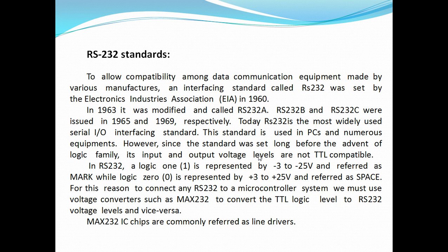These TTL levels are used for microcontrollers for data transfer, but the RS-232 standards were designed before the invention of the microcontroller. The RS-232 standard uses different voltage levels for data transfer. For example, logic 1 is represented by -3 to -25 volt, and logic 0 is represented by +3 to +25 volt.